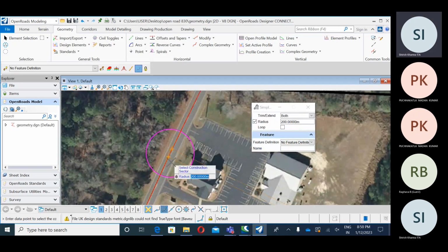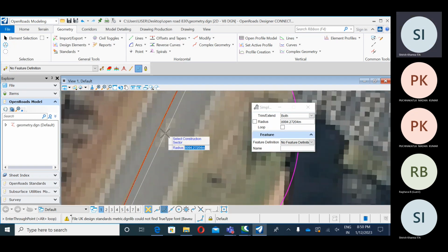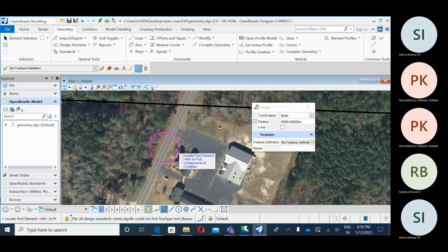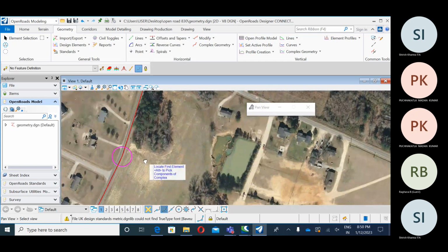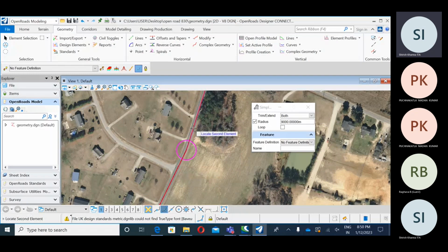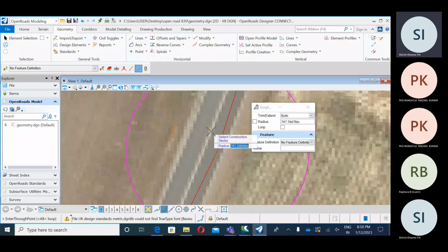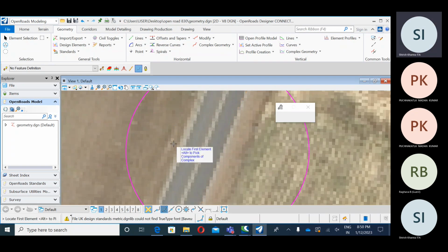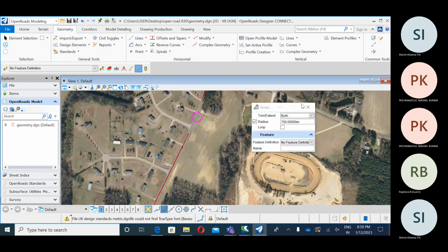Then we go for the second. First element, second element. Pass it to this side. See, it is approximately 9,000. Accept to pick, trim both ends. Now we are going for the next one on this side, first element and second element. I'm passing through this, approximately 750. Take it and click to accept. Now both ends are trimmed. Now it is ready.